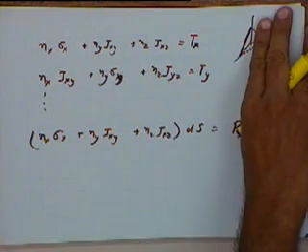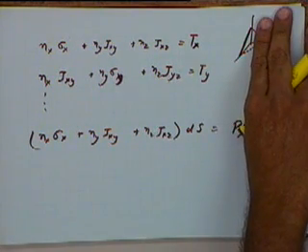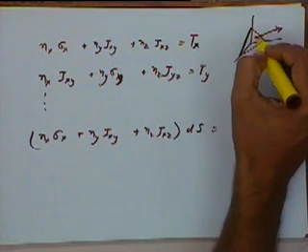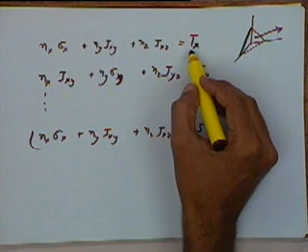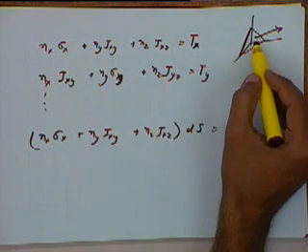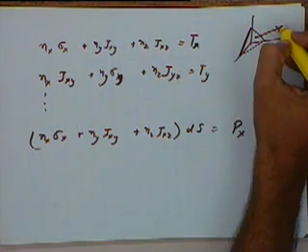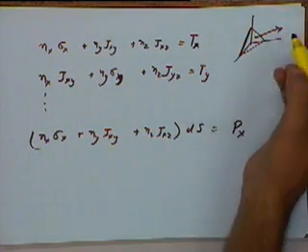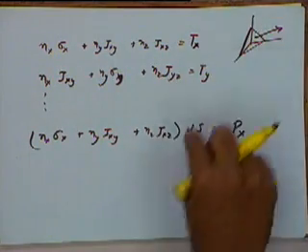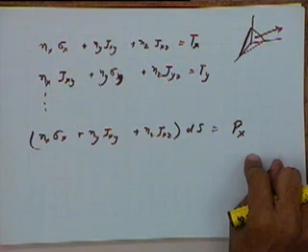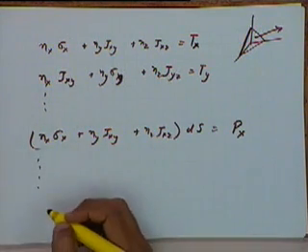If you do not give any point load, then if I integrate over the complete surface, I get a term equal to the total tractive force in the x direction. But if I have a point load, then effectively I multiply by the surface area, and that will be equal to the point load in the x direction. Similarly I will get another two equations like this.